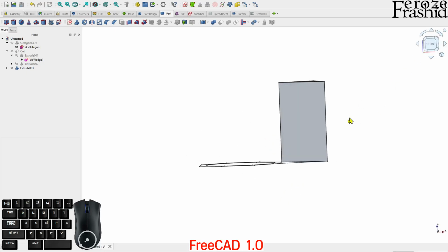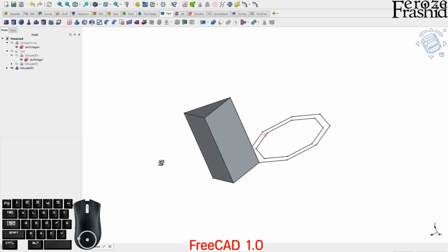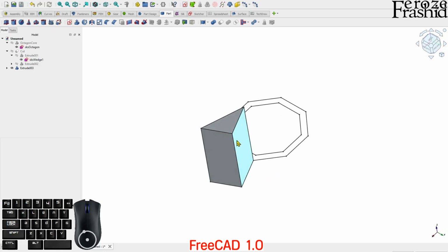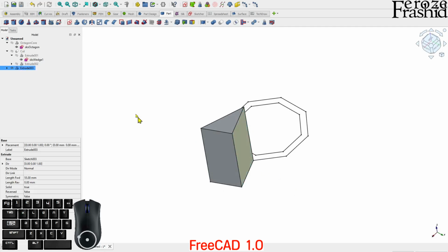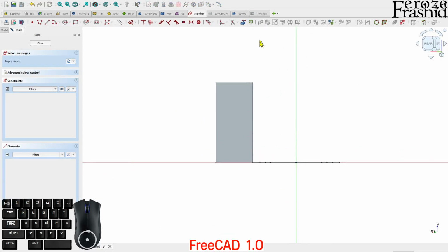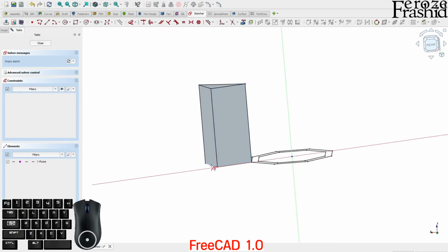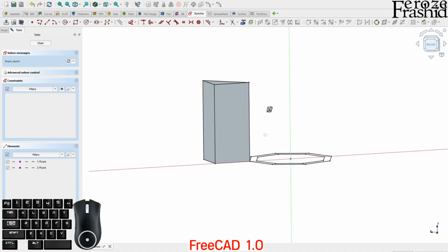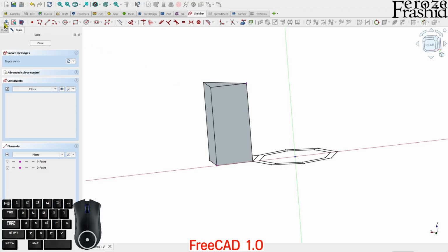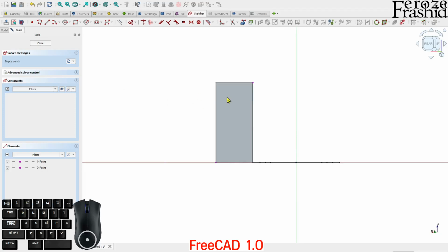I want to draw sketch. Well, I'll have to draw a sketch on this face because I'll have to make it a cut perpendicular to this face. So let's draw a sketch on this face. So select that face, draw a sketch, and say plane face attachment yes. In here, I want to bring in this point, and I want to bring in this line that brings in as a point, right? And so the button from the right, second from the right, that's what aligns our view to the cross section.